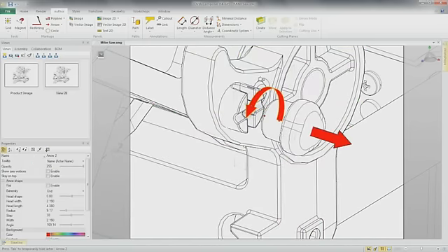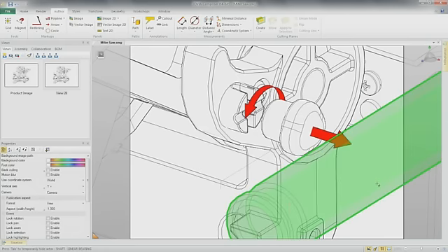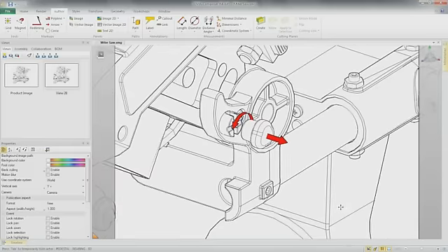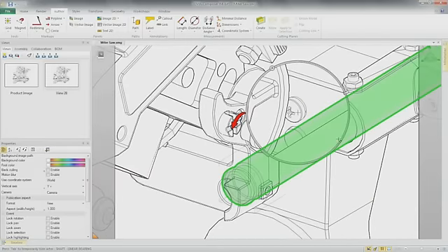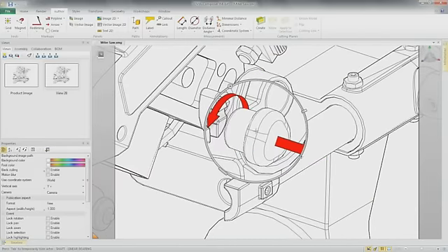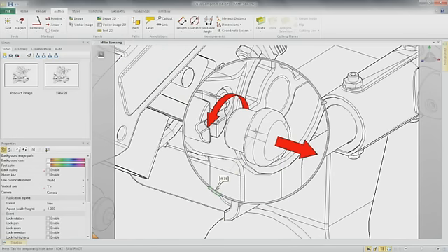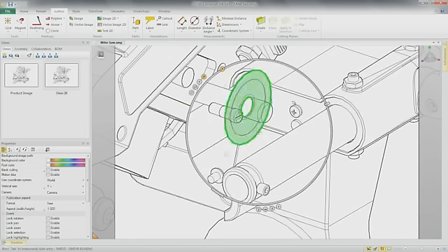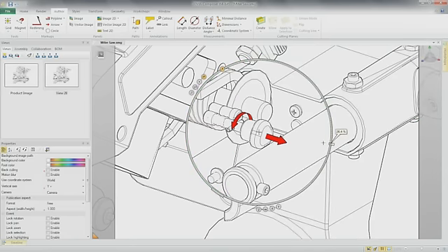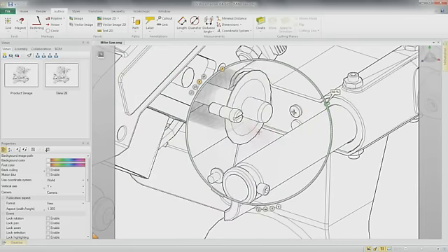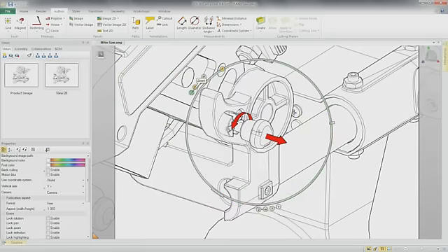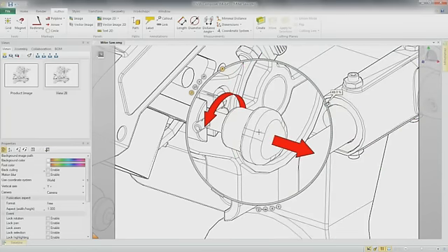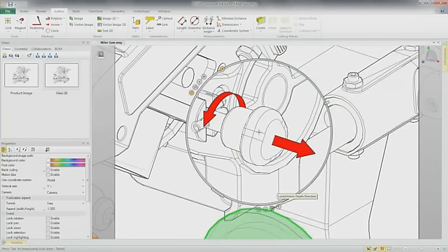Now that we have the arrows how we want them in our view, we may want to call this out, but we don't want to be zoomed so far in. We'll use the powerful Digger tool in Solidworks Composer to do this. It provides a wide variety of different ways of viewing what's underneath it. Choices include an onion skin style, where we can peel away the outer layers of components, an X-ray style, where we can gray out and see through other components. Or in our case, we just want to zoom in on this area of the design.